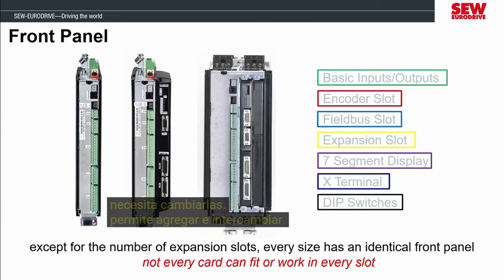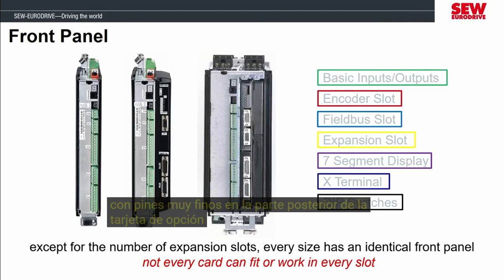You are allowed to add and swap cards as needed. Just be careful with them because you are handling a fragile circuit board that connects to the MOVIDRIVE with very fine pins at the rear of the option card.